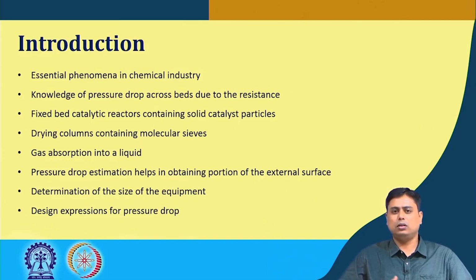Now the point is that in most of the industries, the flow through such packed beds or granular beds, or let's say powders, is not single phase flow. Okay. Multi-phase flows happen in those cases, but for the time being we will focus at first on the single phase flow when it happens through such a bed of material of several different objects of different sizes, that can be of different densities.